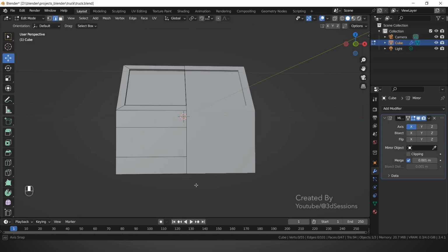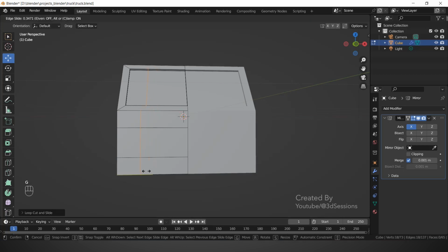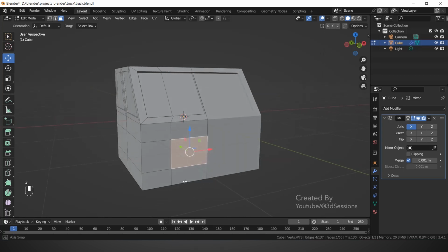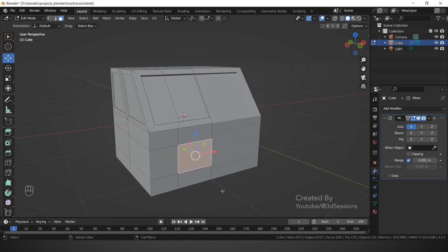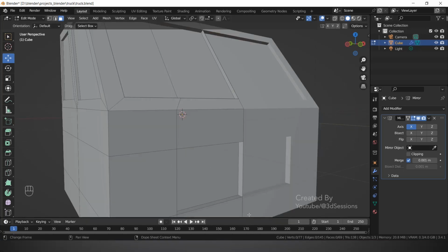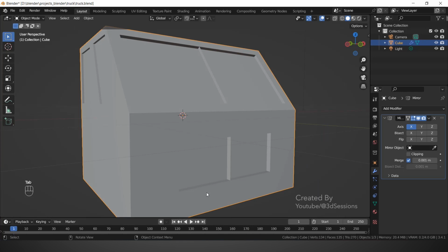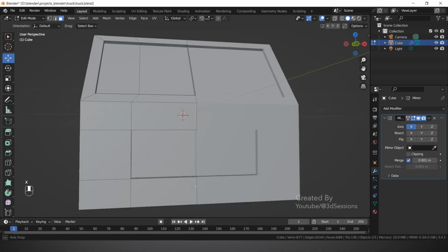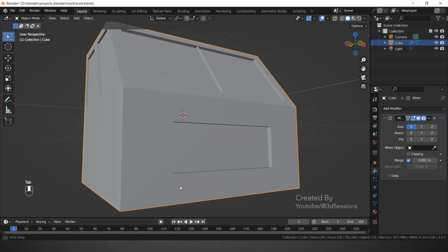Now this is fine. Now add a vertical edge loop, Control R and move it, double G, 2 times G, and this is fine. Now press 3 for the face mode, select this face and extrude it inside, E, and inside a little bit. Yes, this is fine. Select this and delete this face. Yes, this is correct.